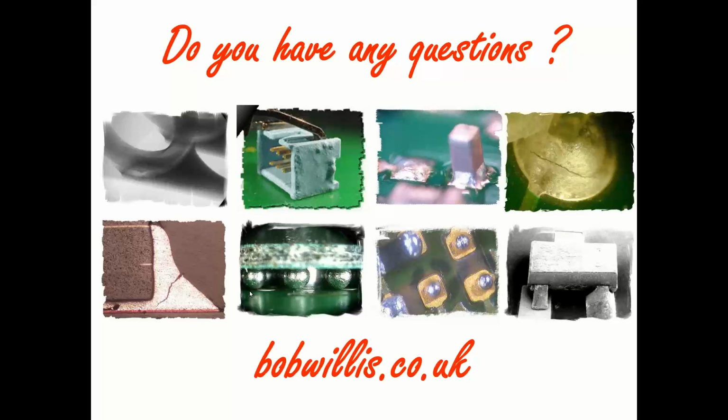When you're talking about components, with certain components, you don't want conformal coating underneath those components. If your product is going to see a high degree of temperature cycling, then you must make sure that the material you're using has the same expansion and contraction rates during temperature cycling as the conformal coating material. So everything has to expand and contract at the same time.